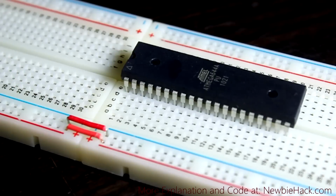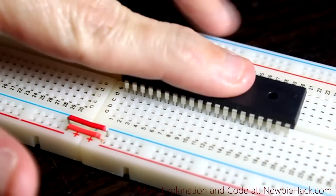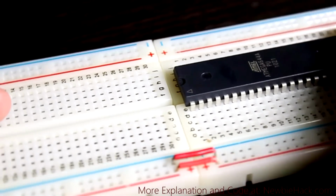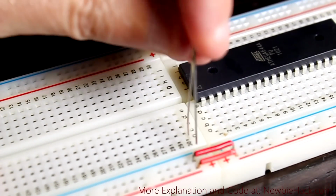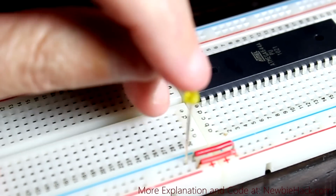So let's go ahead and put the circuit together. I'm going to be using the ATmega 644 because I can't find my 324P. This is the 644A. Fortunately, the 644A shares the same fuse bits as the 324P. I'm going to add an LED. And we'll connect it to the pin B0.